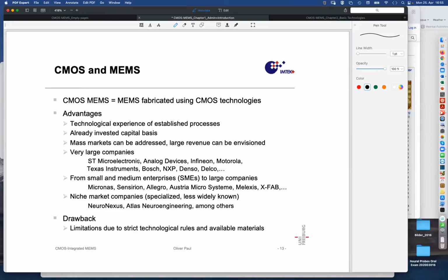1,000 by 1,000 or 1,280 by 768 little mirrors that can be flipped to either side, to white or dark, many times per second, with many filters passing in front, and to have a color image, three of them illuminated by three different colors.